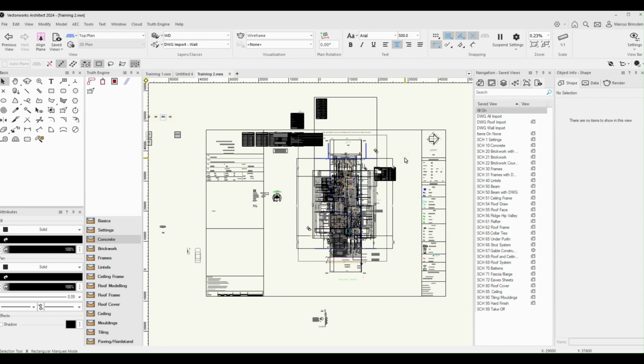A layer in Vectorworks is more like a sheet. You have your sheet layers and design layers. You can think of them as separate stories or different sheets, but each has its collection of classes that go with it. There's sort of two ways of controlling what's visible.